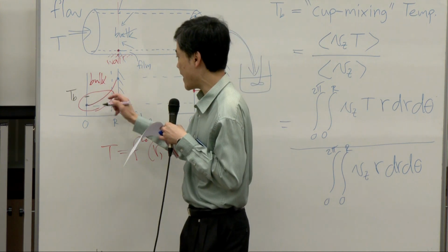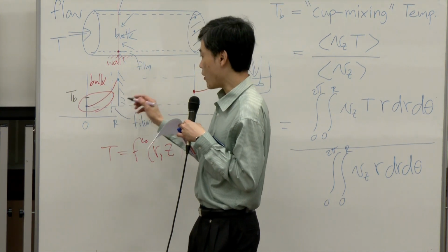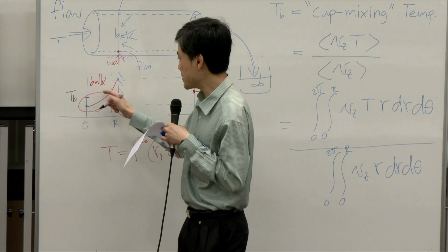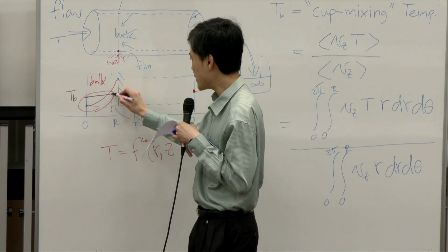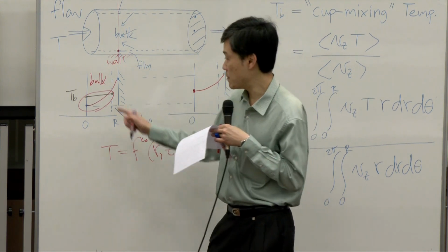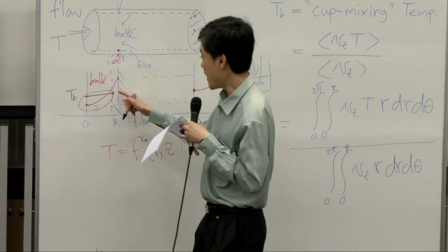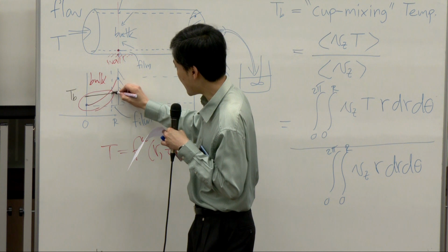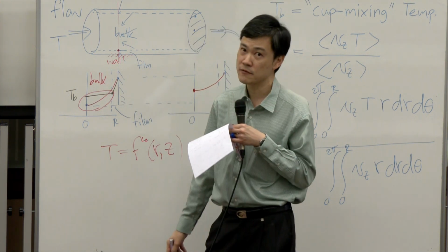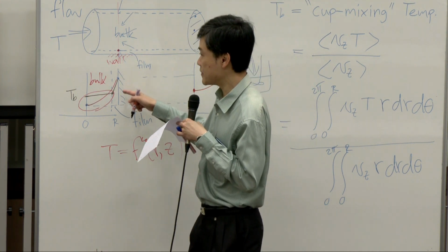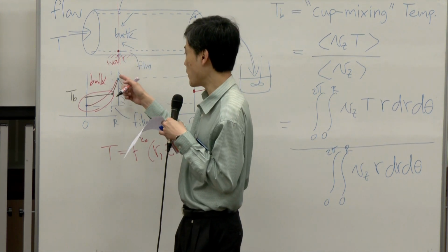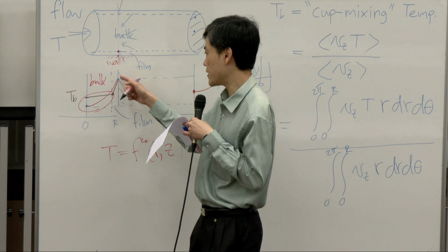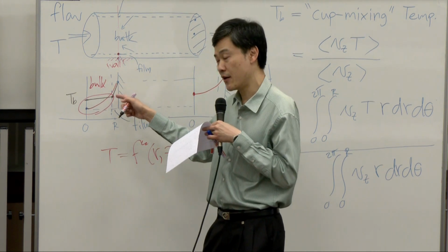So from now on, I would assume that whatever is inside the bulk has the same temperature until it reaches the interface between bulk and film. And within the film, it stays as a linear temperature profile, just as what we did in the heated wall. So within the film, there will be conduction only, and temperature profile becomes linear.